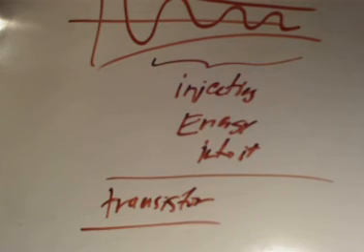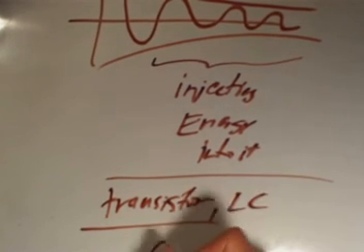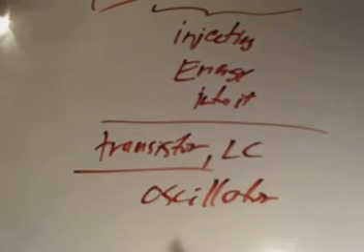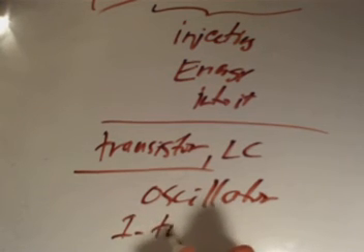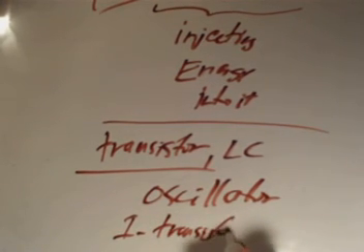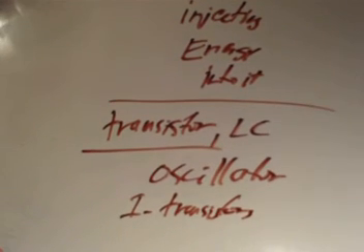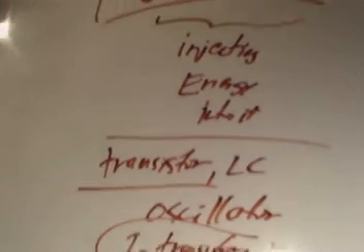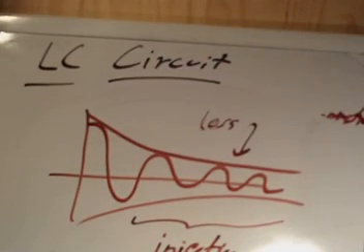And so if you go to Wikipedia or something and look up transistor LC oscillator, if you're lucky, you'll find someone who will present a circuit that involves just one transistor. A very beautifully simple circuit. You'll see the capacitor, you'll see the resistor, you'll see the battery supply, you'll see this one transistor in there, and when the thing is turned on, it'll oscillate forever and ever, at least until the battery goes dead. And it's a way of making a radio tone transmitter. But anyway, that's the LC circuit. The important takeaway is that logic, again, about how the charge leaves the capacitor, goes into the inductor, and from the inductor back into the capacitor, and hopefully you can reproduce that logic.